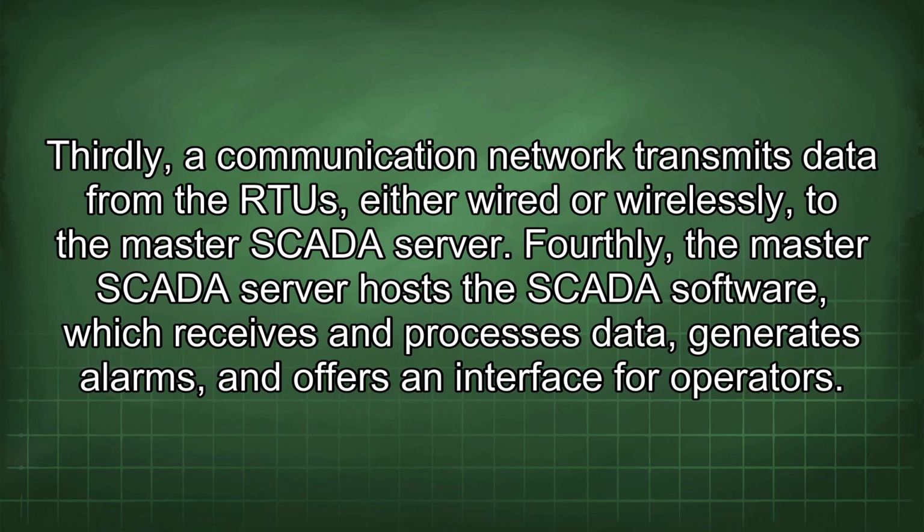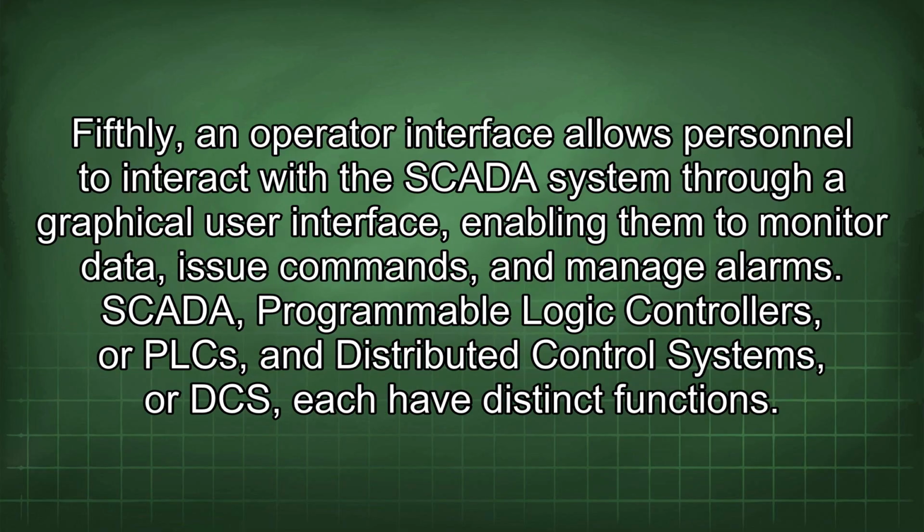Fourthly, the master SCADA server hosts the SCADA software, which receives and processes data, generates alarms, and offers an interface for operators. Fifthly, an operator interface allows personnel to interact with the SCADA system through a graphical user interface, enabling them to monitor data, issue commands, and manage alarms.